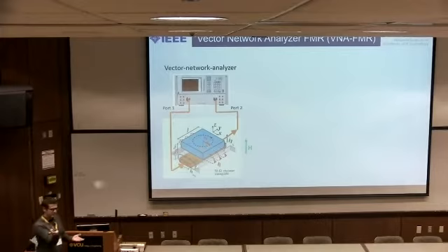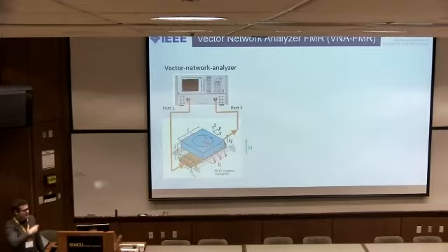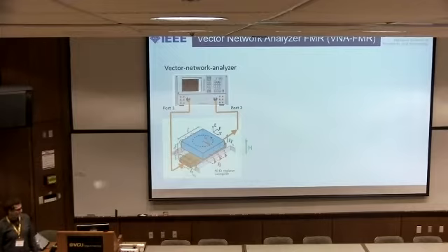And if you take your sample, a thin film sample, and you put it face down on that waveguide, as shown in blue here, then those RF fields can interact with your sample. And that'll change the transmitted microwaves through this center conductor, which are then measured and picked up on the second port of your VNA, shown here, the receiver port. And of course, you can apply magnetic fields. In this case, it's a perpendicular magnetic field here.